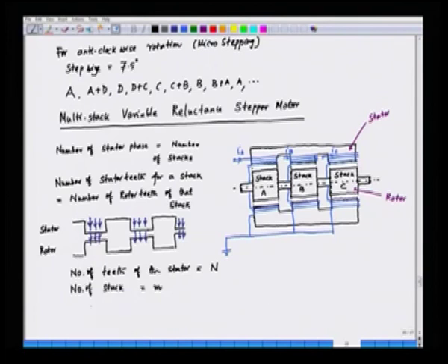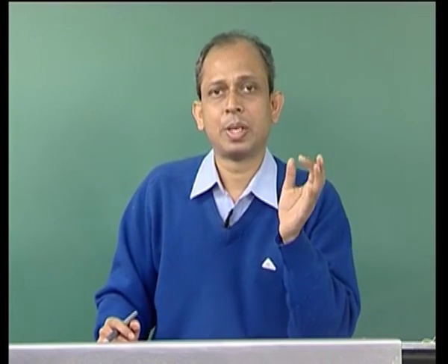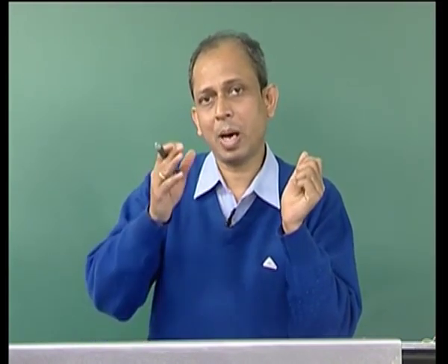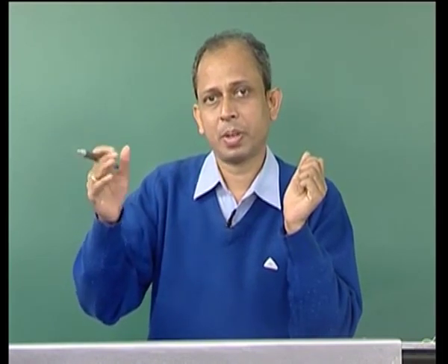We can say that the stator tooth pitch is equal to 360 degree divided by N, because we have N teeth in the stator and one mechanical revolution is 360 degree.